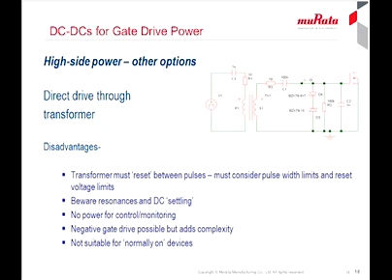Another way to drive gates is directly through a transformer. This provides isolation and is relatively simple, but the transformer will be a compromise because it may need high isolation and watts of power, but at the same time it is transferring the PWM signals at high frequency like a signal transformer. Practically, it cannot be optimum at doing all these things together, so it will be limited to relatively low PWM frequencies, which makes it physically quite large.